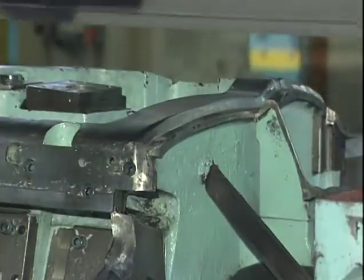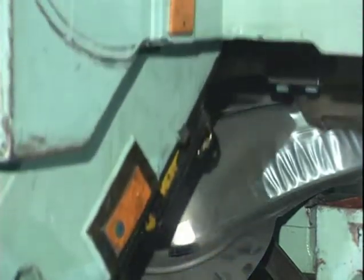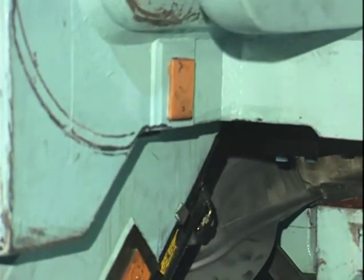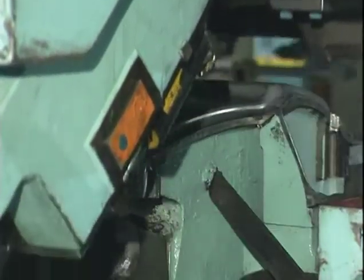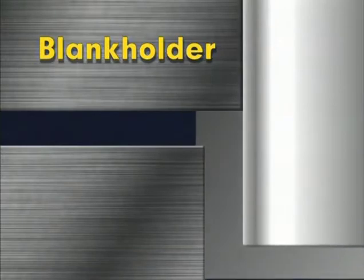Compressive forces on the metal in the area beyond the die's edge will cause the metal to buckle. If this metal were pulled into the die, buckling would increase until the metal ruptured. To prevent buckling, the blank must be held tightly by a blank holder.